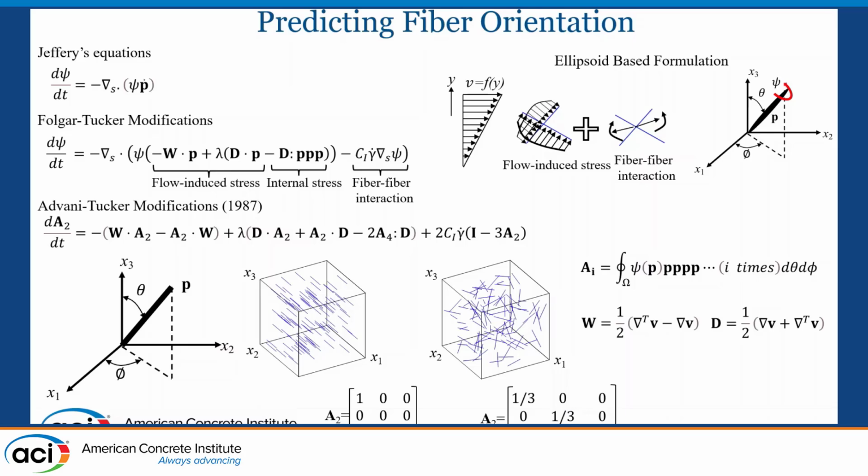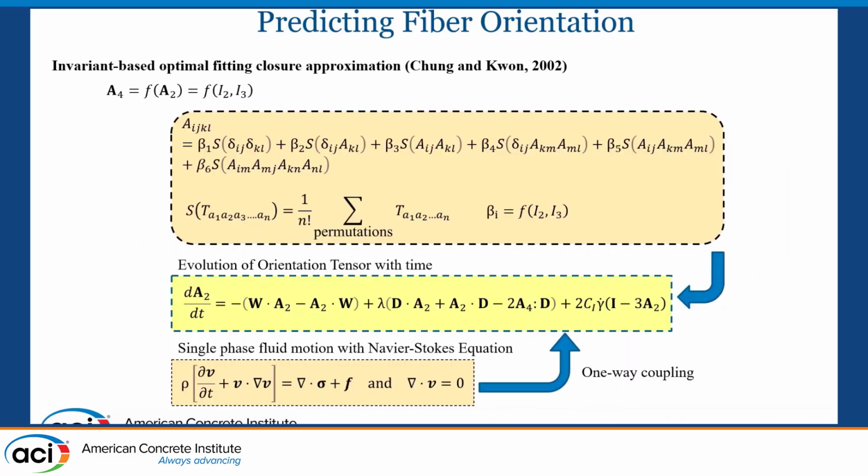So the total probability adds up to 1. I use this model, and using CFD data, I predict the fiber orientation by solving this differential equation. After solving it, it's a one-way coupling. We just inform the fiber orientation from the fluid phase. We do not do the back coupling from the fiber due to hydrodynamic interaction because of computational cost.